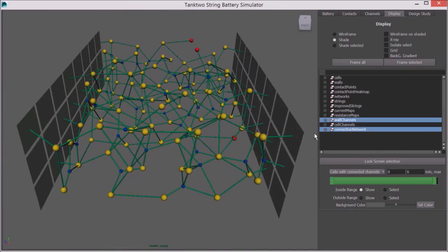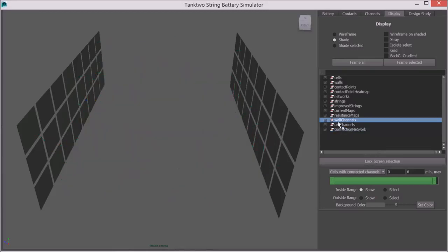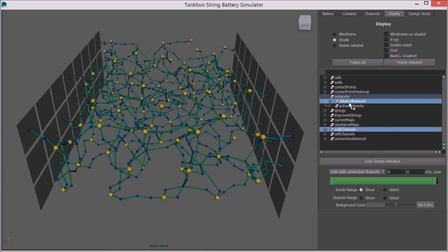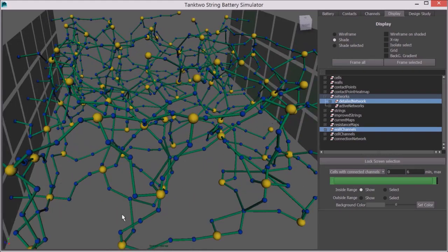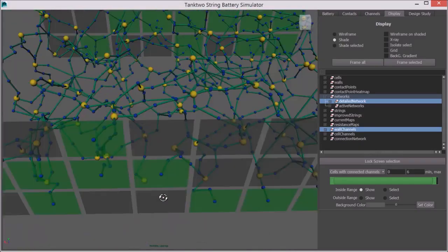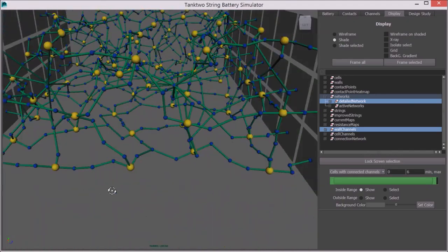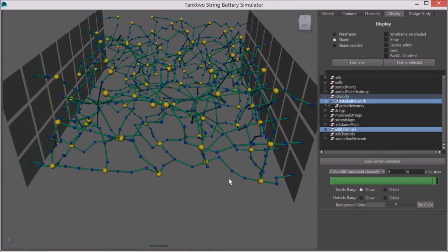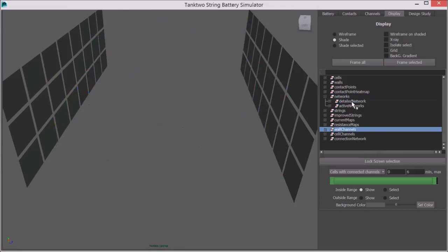On detailed network representation you can see even more details about the connection network. Here each connected terminal is represented as blue node next to the cell. This network is used as a starting point for all routing algorithms. After the cells are placed in the battery container, the first problem is the network mapping, so that the location of each individual cell in the network is known.